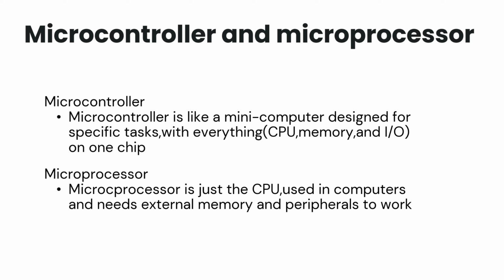Timers operate based on internal and external clock signals of the microcontroller. The clock system provides the timing reference of the microcontroller and determines the speed of instruction execution. Microcontrollers can use either an internal oscillator or external crystal oscillators, depending on accuracy and performance requirements. Along with this, a microcontroller also offers power management features such as sleep and idle modes, which help reduce power consumption.